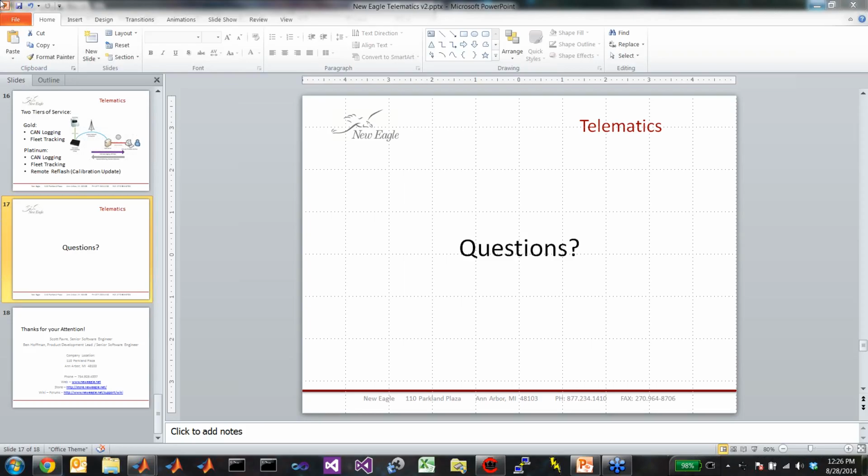Well, in addition to providing the Simulink library that facilitates the communication, if we are working with you on the application, we could help figure out how the update can be done safely, what needs to be done in terms of shutting down systems that are active, making sure nothing high voltage is going to be suddenly let loose in an unknown state because we're in the middle of a reflash. Those are the sorts of things we can work with you on to help figure out how to do a remote flash safely.